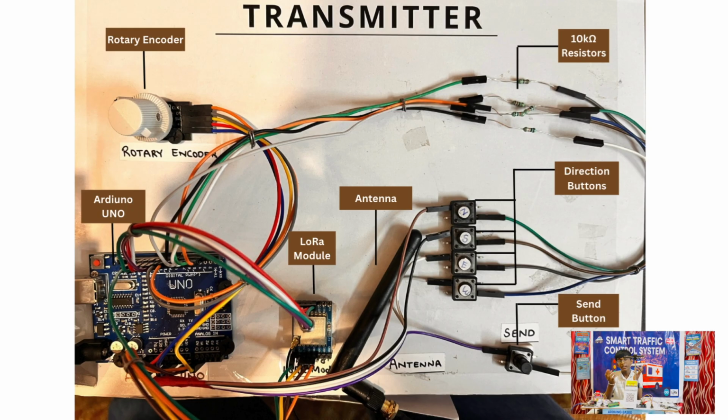It transmits data around a radius of 1 kilometer actually, but they have told 2 kilometers, but it's not actually working for 2 kilometers as we have checked. This one comes with an antenna used to transfer data, and the common configuration of this one is SX1278, and the frequency is 433 megahertz.